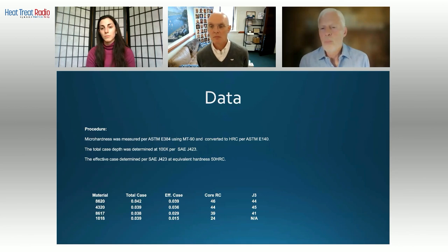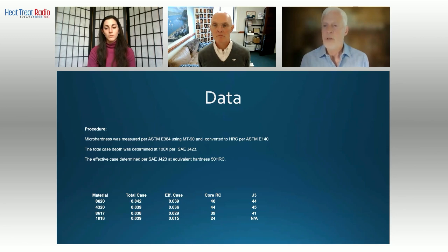It's multiple pours out of a tundish. And the chemistry and the hardenability numbers that you get in a steel certification are going to be very close to an arithmetic average of what you would get when they test the first pours and the middle pours and the end pours. They're going to average those things out.